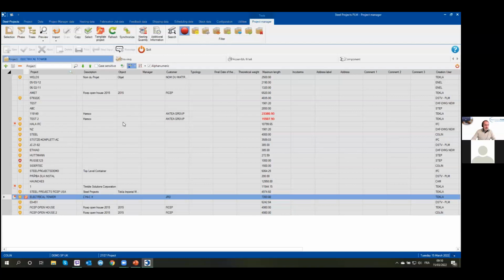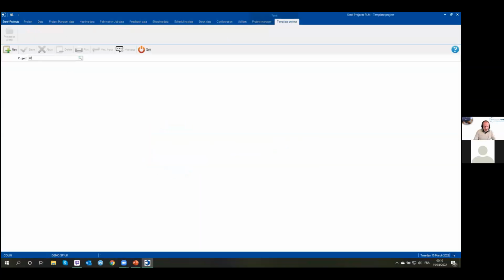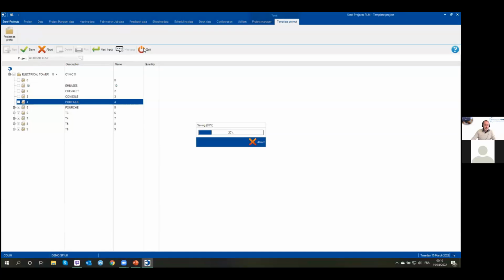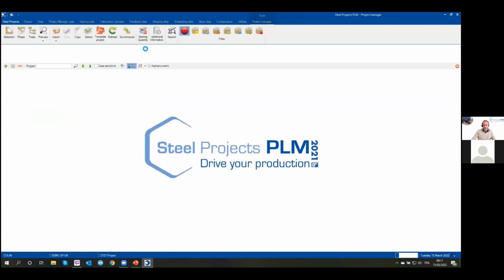So I just have to click here on template project. Here, I will create a project called webinar test. I will create it, yes. And I will say, okay, from my template project electrical tower, I want to use, for example, those 5 phases, 5, 6, 7, 8, and 9. I will validate here. So out of this template project, I will create a new project taking all the phases I want.